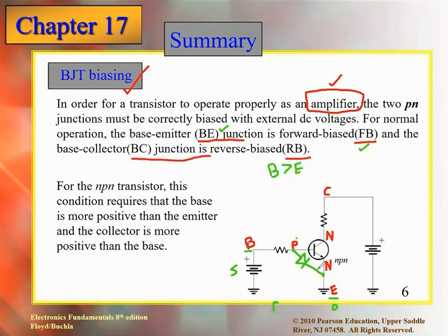Correct. So this is in forward bias, which we have set up now. Just look at the other junction, which is base collector. Because it is again P type, it can also be considered as a diode. For simplicity, to explain the concept, this is P, this is N, and I want to make it reverse bias. We have already set up the voltage at B. I have to set up the voltage on C. How much voltage should I apply compared to B so that it is in reverse bias? Just say greater or less than.